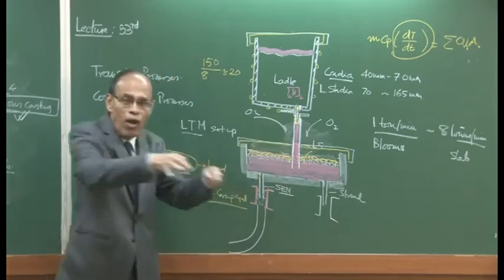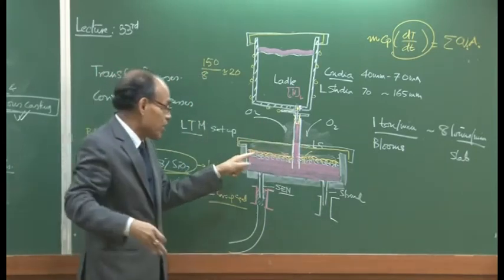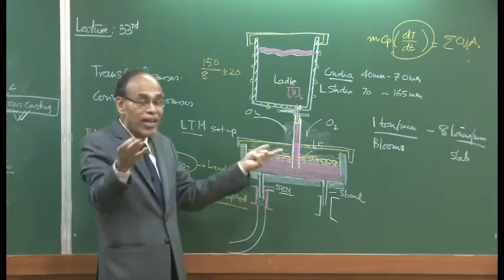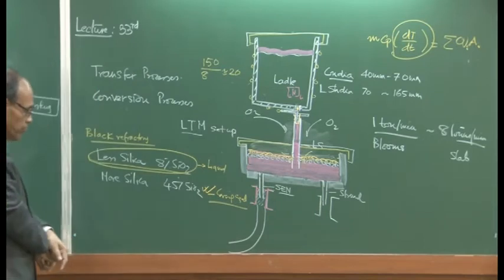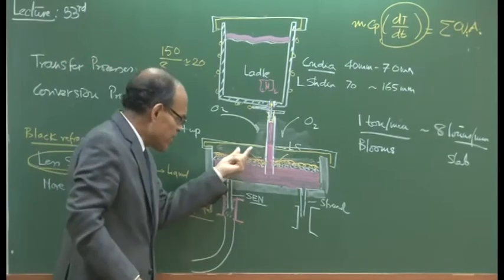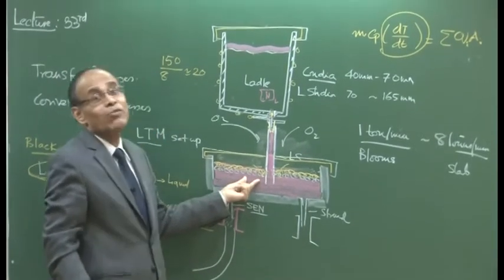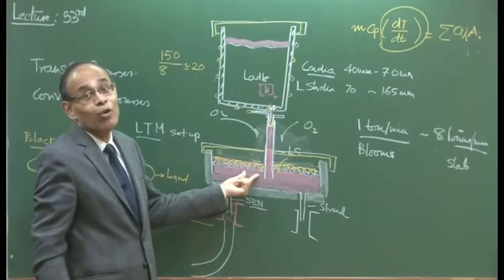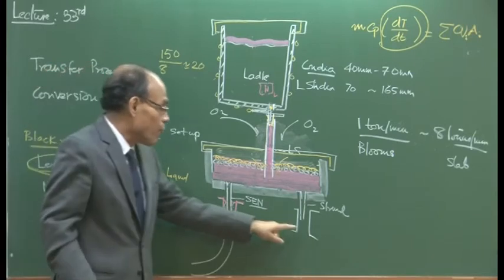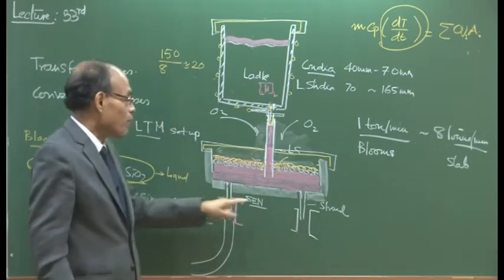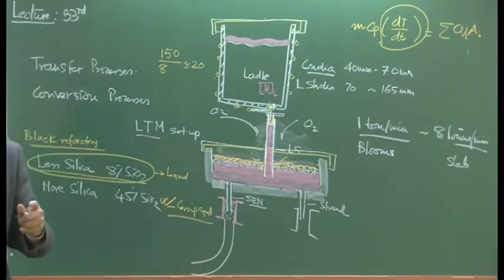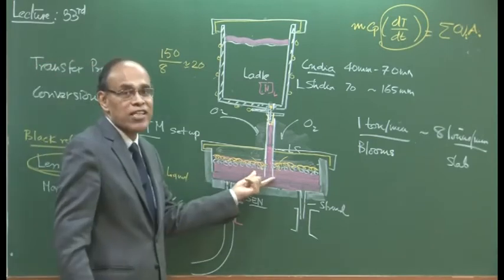Initially we want a lot of material from the ladle to go, because the quicker the tundish shroud tip submerges into the molten metal, the less air-steel interaction there will be. If there is a significant amount of air-steel interaction, the steel will become dirty, because dissolved aluminum will react with oxygen in those turbulent mixing zones. As a result, the first bloom or the first slab which comes out is never sold as prime product, because it will be the result of reoxidation in the tundish itself.